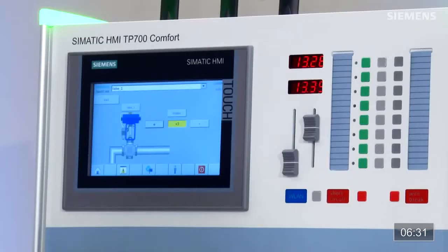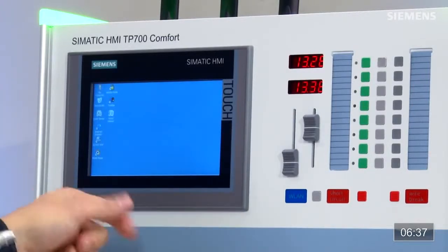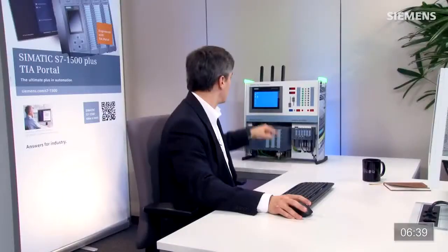Until I reestablish connection, does it actually blow it up? Well, let me actually shut down the runtime. That's the easiest way for me to do this. Once the runtime is completely shut down, it'll give us the ability to restart. Once I do restart, it's actually going to try to reconnect to a protected CPU at level 4.